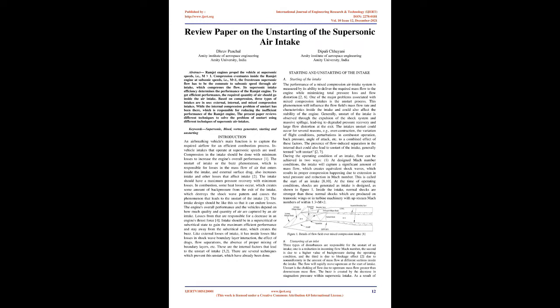While in internal compression the problem of unstart has been there, which is responsible for reducing the performance of the ramjet engine, the present paper reviews different techniques to solve the problem of unstart using different techniques of supersonic air intakes. Keywords: supersonic, bleed, vortex generator, starting and unstarting.